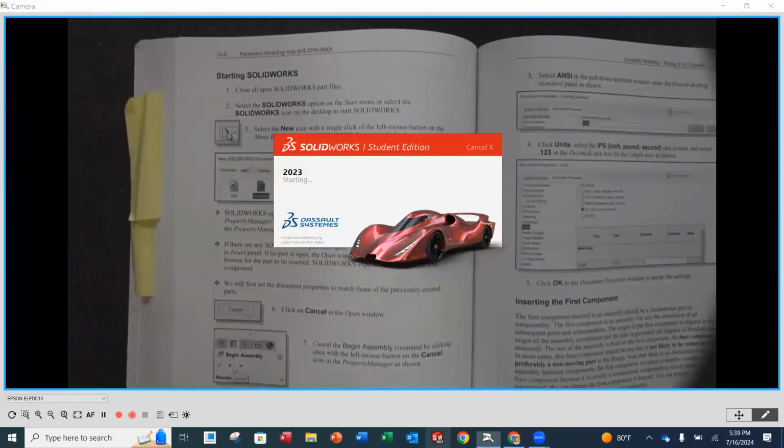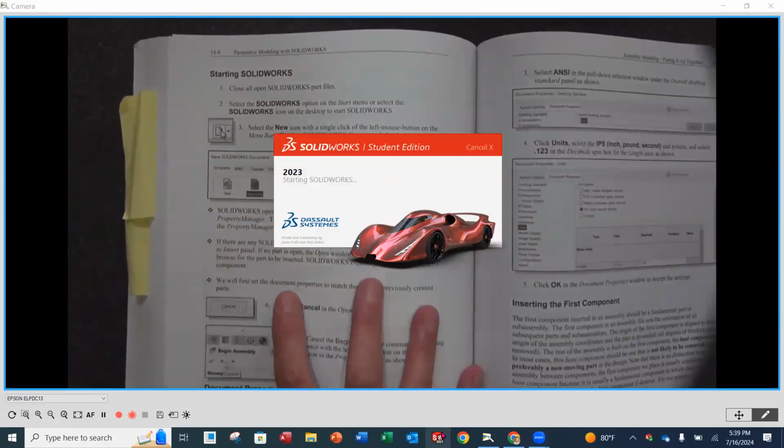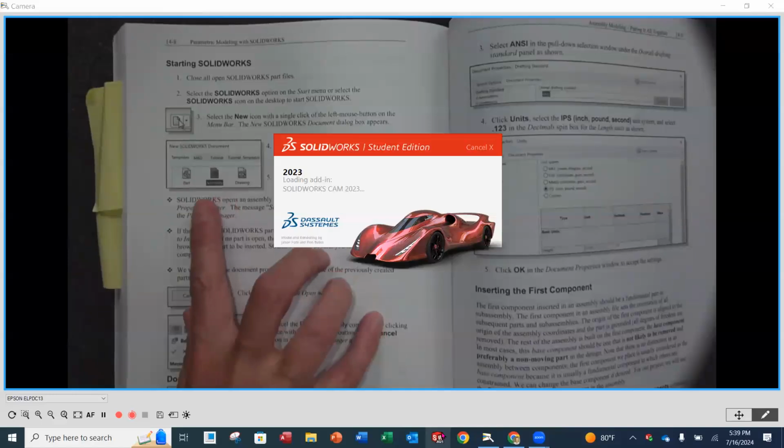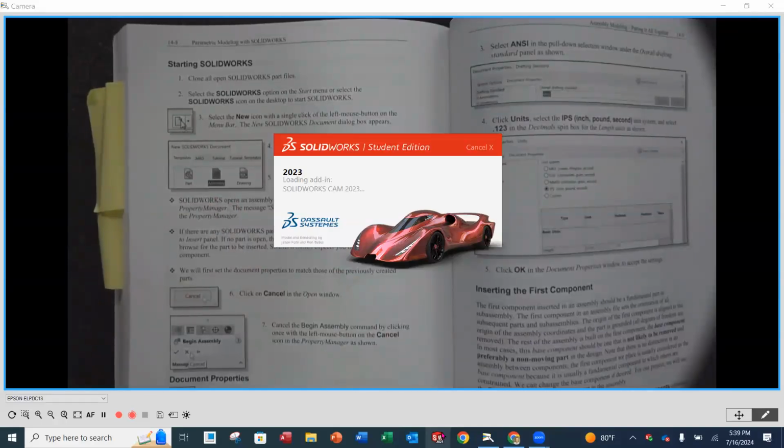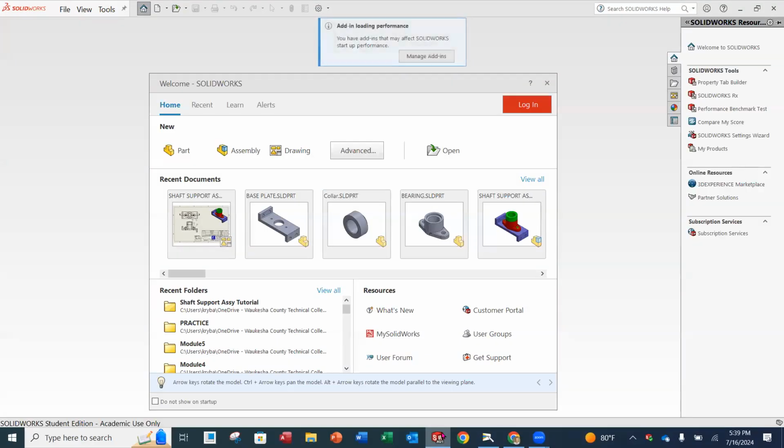And then here is where we start the tutorial for actually an assembly. Now, I'm going to open up my SolidWorks. Some of you already have done this because we've talked about it, but I'm going to go underneath to SolidWorks. I'm going to open up. And this time, you can kind of see here, instead of picking a part, we're going to be picking the assembly template.